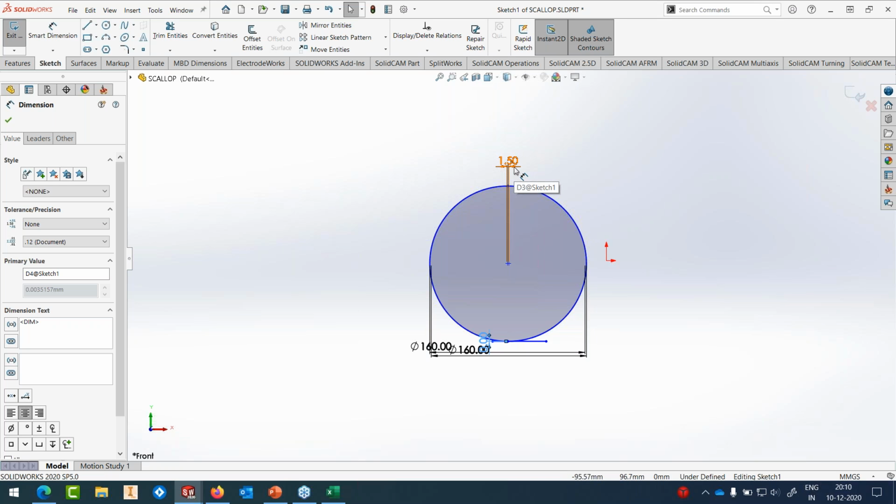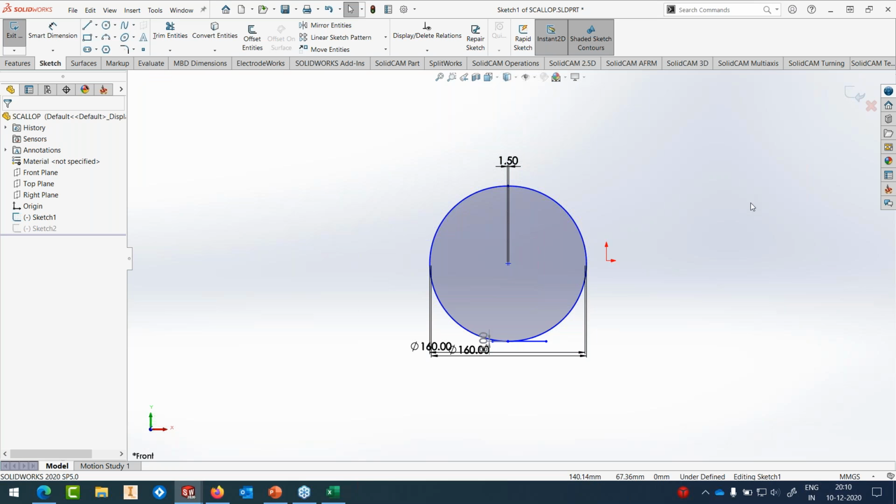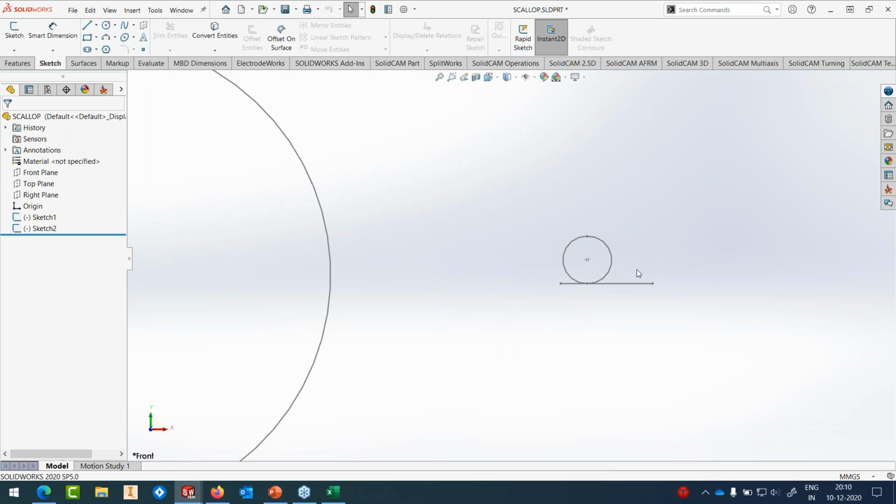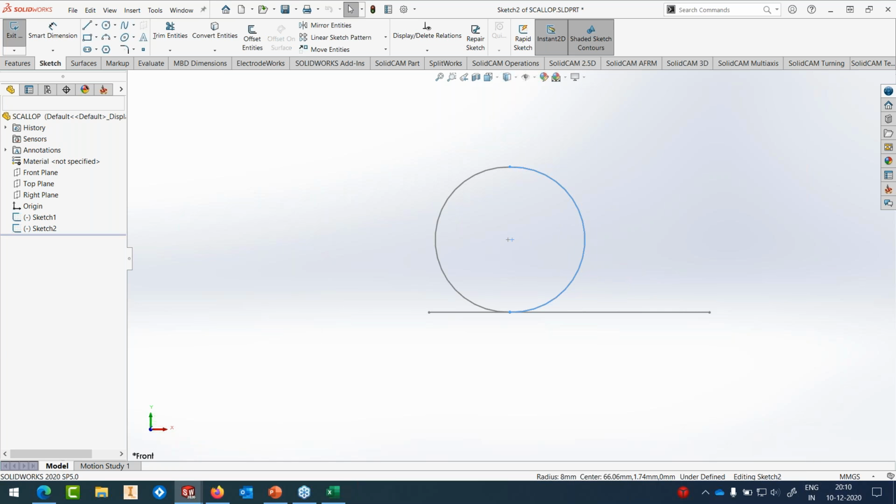So if I take a step down of 1.5 millimeter with the oval form tool, I will get a 3 micron scallop on my wall. Now, if I want to achieve the same 3-micron scallop using a ball nose tool, because if it is deep then I have to use 5-axis and tilt the tool, I would need to take a step down of 0.5 millimeter. This means machining with an oval form tool is at least 3 times faster as compared to a ball nose tool.